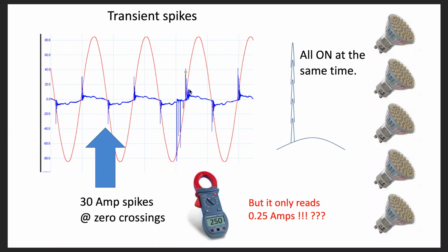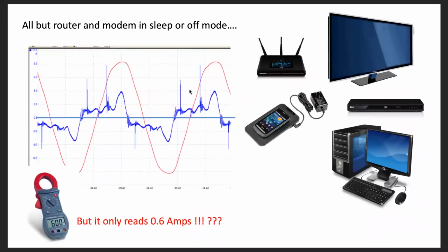If you've got a lot of home electronics, for example, a home office with, say, a laser printer and a few other devices with those switch mode power supplies on them, you can mitigate the transient spike effect by putting on a UPS, just a standard home office uninterruptible power system. It will filter out those transient spikes from the Evolve battery, protecting it from tripping offline in backup mode. And it'll also provide the added benefit of protecting those devices from that 4-second outage when the grid goes down. That would be for these.